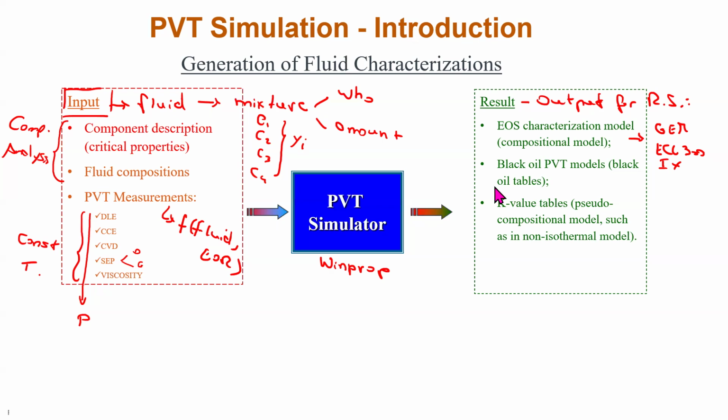However, you still need to run characterization of your fluid using a PVT simulator to calibrate the data that you have available in this area to generate the PVT tables. So the PVT table is called the black oil table as well. So it's another name for the same thing. So you can call the input to characterize the fluid a black oil table or a PVT table. So this is the input, for example, for IMEX using CMG, or for Eclipse 100 using software from SLB.